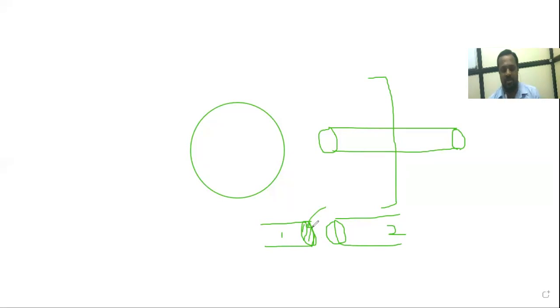Sectional view is nothing but, whenever we require internal information, at that time we cut one of the components by using an imaginary cutting plane, and we divide that component into two parts. After the cutting, how that internal part is looking, that part we show by using the hatching line. Okay, look at an example. You know the apple, have you all seen it?